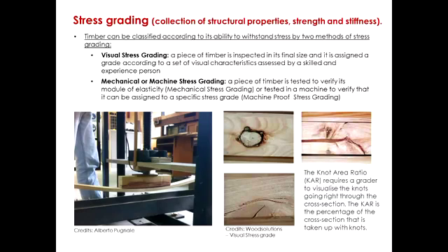We use 1 meter as the span to make sure that we can use it as a unit, as a multiplier. We just check how far we can go with that bending test. We can increase the amount of force applied and measure the deformation. At the same time, we know the deflection that is used to calculate the modulus of elasticity, and we know the amount of force applied to reach that level.